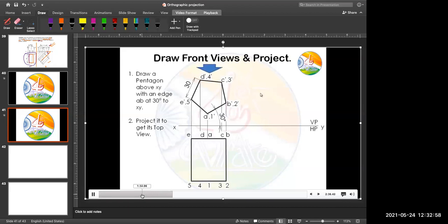For that, we have to watch the diagram from the opposite side. In this diagram, we see that B and C appear first. So the edges from B and C are visible and have to be drawn with a dark line. Whereas the edge coming from A is hidden behind the face, and hence should be drawn with a dashed line. That's it.